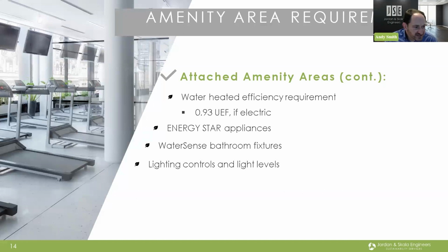Okay. And James, I got another question that came in with respect to the electric heat. He says, I assume the auxiliary heat in a split system heat pump DX system is still allowed, correct? That is correct, because we do need that emergency heat. For those that don't know, heat pumps pull heat from the air down to cool temperatures, but there certainly is a point where it's too cold outside to pull heat from. And so in those situations, there is emergency auxiliary heat, this resistant strip heater, to ensure that your tenant remains having a good heating source.